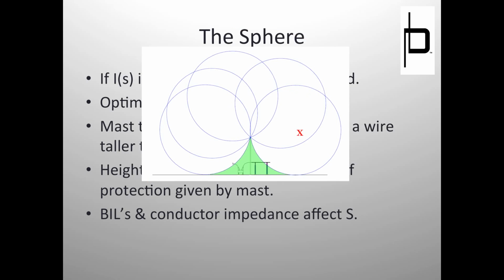All right. And you remember this picture, same illustration here. We said that this piece of bus was in danger from a step leader forming where this red X is, because a step leader here cannot quite reach the mast, but it can reach this equipment. But that's assuming that the stroke current is exactly the magnitude associated with this blue circle. What if in reality the stroke current is a little bit bigger? If it's a little bit bigger, now it can reach the mast. And now a stroke forming at the origin point of this step leader is no longer dangerous. If it has the magnitude of the red circle, it will strike the mast instead of striking this bus. So this is only dangerous for a step leader forming in this exact location and with this exact magnitude.